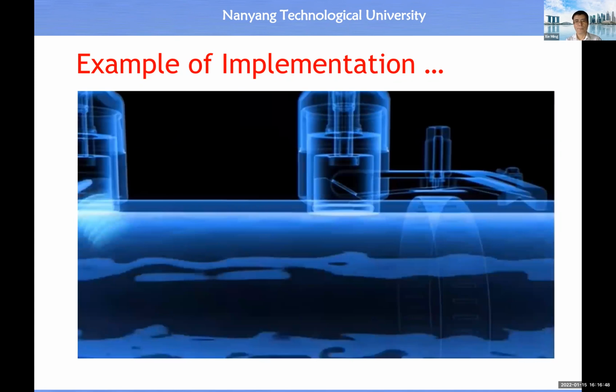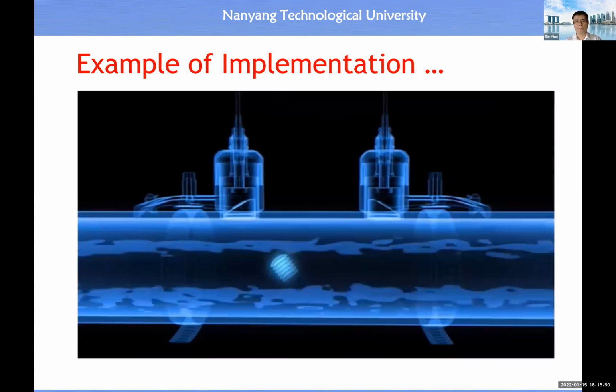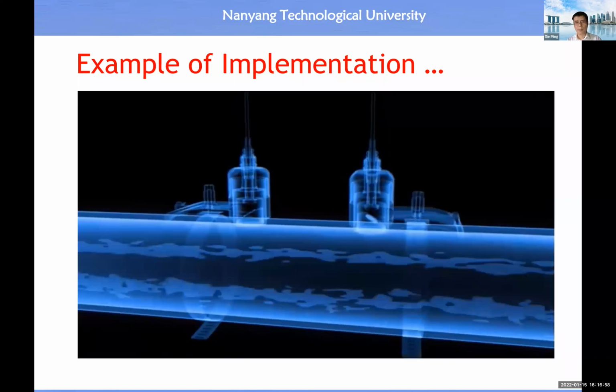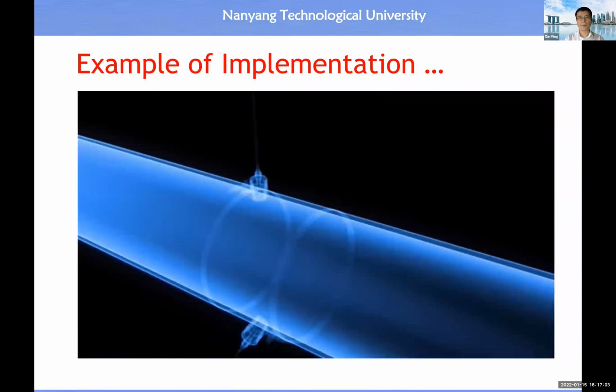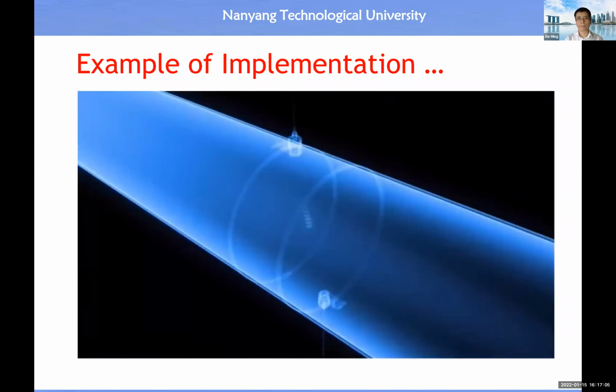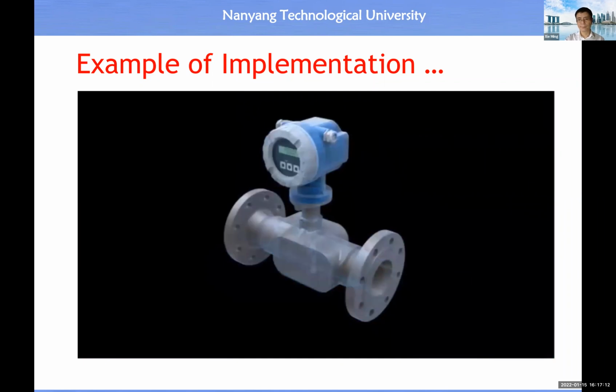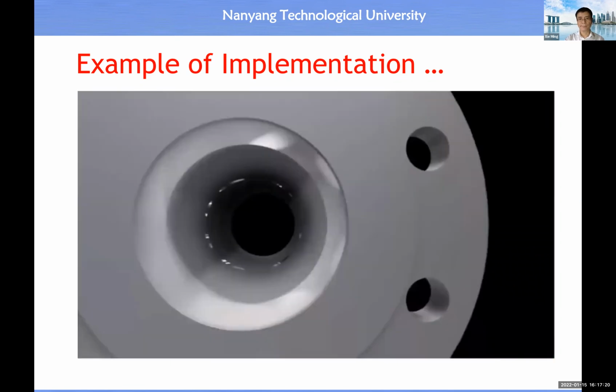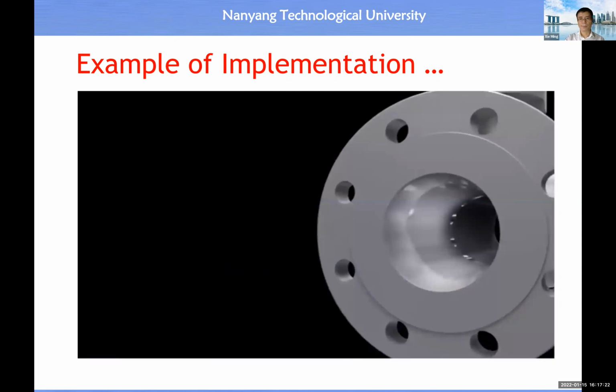In this example, with a two-traverse installation, the clamp-on design is unique because flow rates can be measured in very large pipes, up to 4 meters in diameter. This possibility increases the areas of application, for example, in the water and hydroelectric industries. Flexible mounting, process safety, and cost effectiveness are the distinctive advantages of ultrasonic flow measurement.